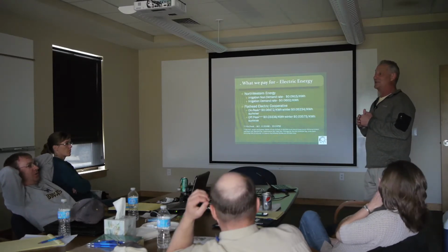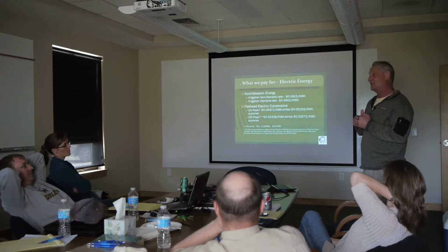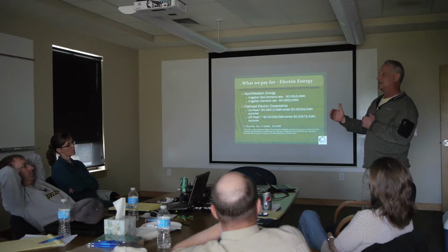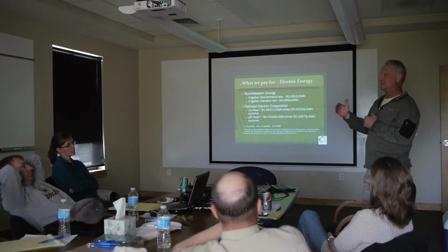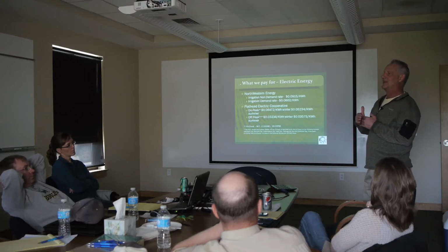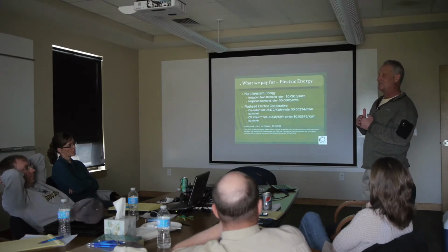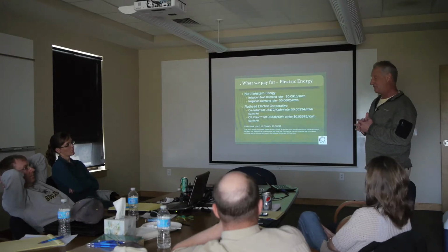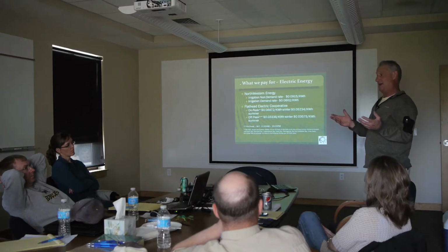Okay, so at 35 cents a kilowatt hour, solar electric is cost effective. So what we did was we sized the solar electric system just to produce that energy that would bring that top rate down for that customer to make it cost effective. But in Montana, normally it's the other way.